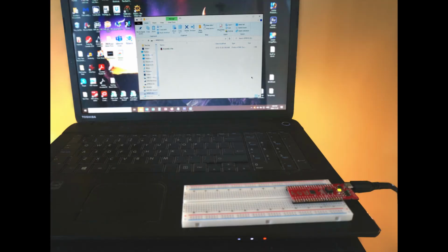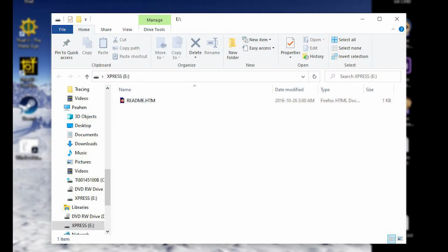This video will show you how to configure PuTTY to talk to your microchip. However, we first need to know what communications port your computer is using to talk to the microchip. So the first thing you should do is plug in your microchip to your computer, as usual, using the USB cable. Also, as usual, the Express Data Storage folder will open on your desktop. We don't really need it, but you can leave it open.